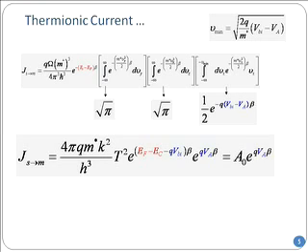Very similar, but also very different. If you remember metal semiconductor, if you remember the PN junction and the expression for it, do you remember that upfront for the minority carriers there was this Ni squared divided by Na, Ni squared divided by Nd, that was a prefactor? That prefactor says that PN junction current is extremely temperature sensitive. Why is that? Because Ni squared has exponential of Eg over kT, and the band gap, because Nc, capital Nv, e to the power Eg over kT, right? And the band gap itself is extremely temperature sensitive. As a result, the prefactor is very temperature sensitive.